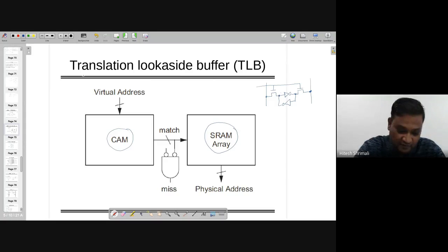So you know how to do that with the access transistors and the driver transistors of these two NOT gates. So this is bit and bit bar, and this is word. And by the way, this particular bit you're going to call Q, and this you're going to call Q bar, right?